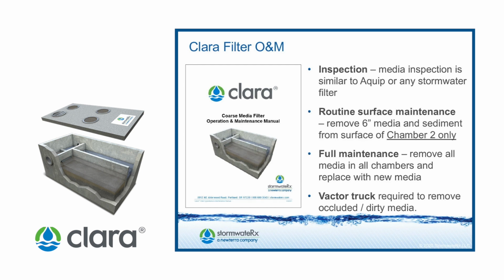Maintenance activities with the Clara filter will require a Vector truck and crew. Because access to the vault is rather simple, the expected time on site will be kept at a minimum. We anticipate less than 2 hours by the crew for a full maintenance to be completed. Lastly, and more importantly, disposal of the inert media should follow any local, state, or federal guidelines.